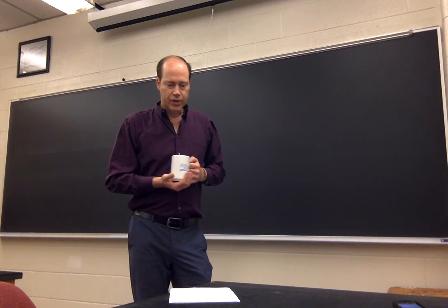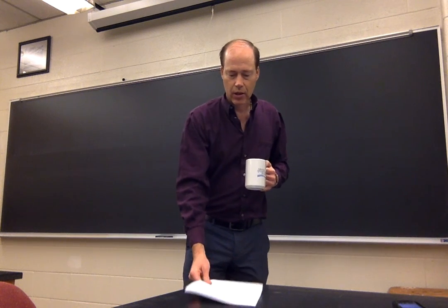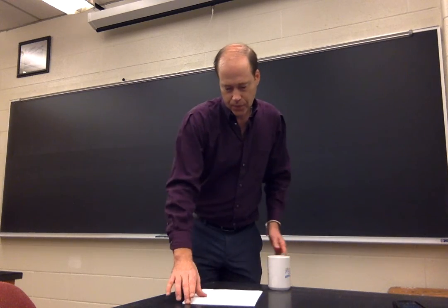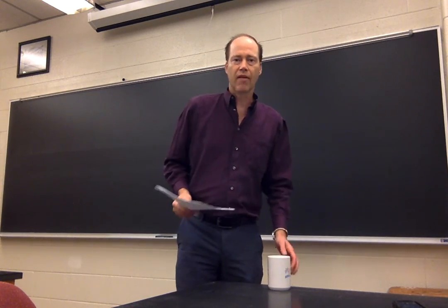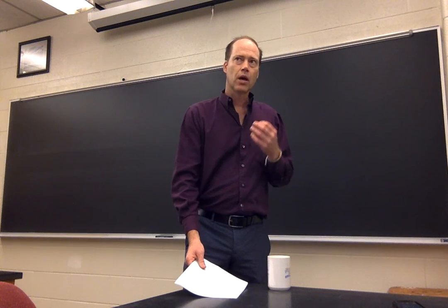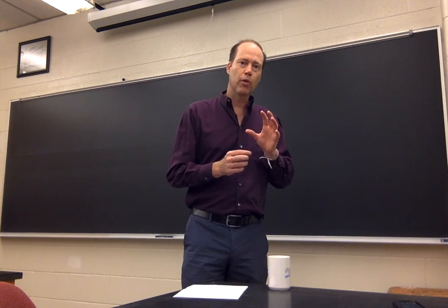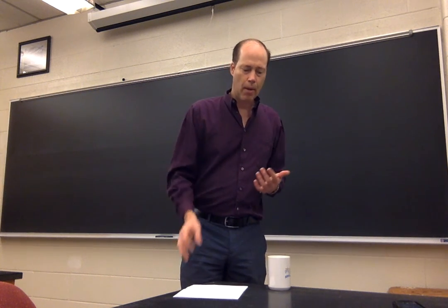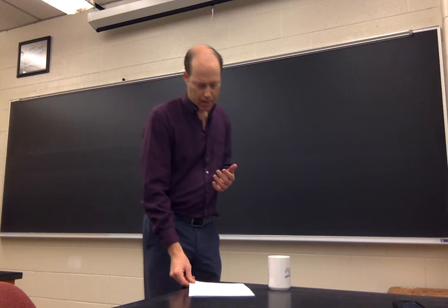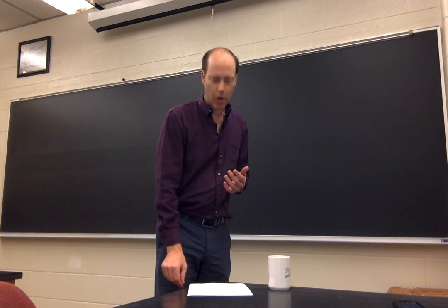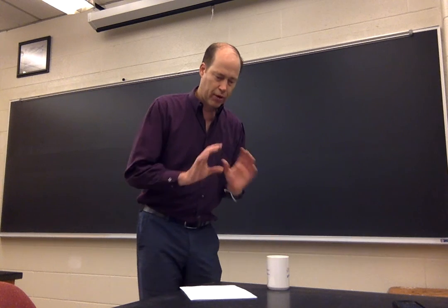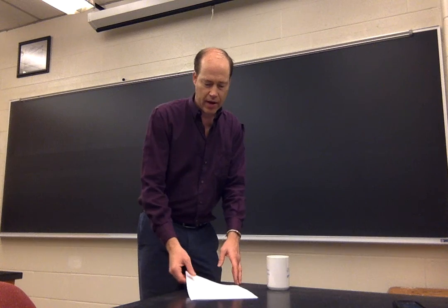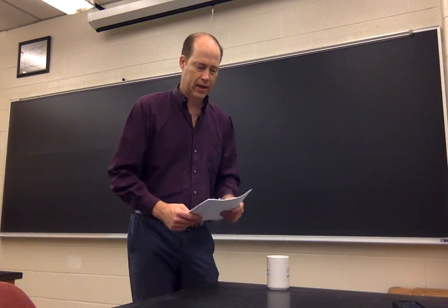Good morning. This is Lecture 7 in Elements of Hydrology, and this is the last of the lectures that deal with fluid mechanics. And in this lecture, we're going to derive Poiseuille's equation, which helps us assess the velocity profile of water in a pipe. And in the end, we come up with an equation that allows us to calculate discharge in a pipe given a pressure gradient and given an elevation change and given a specific type of fluid that is moving through there